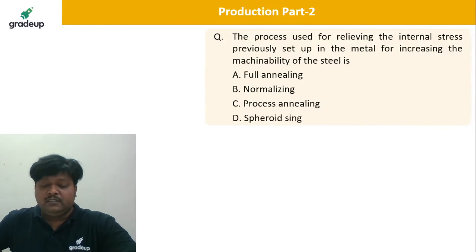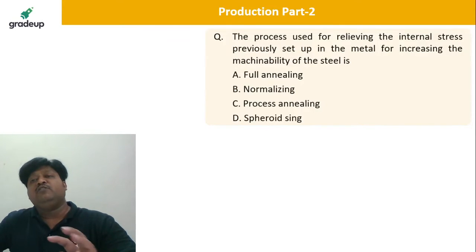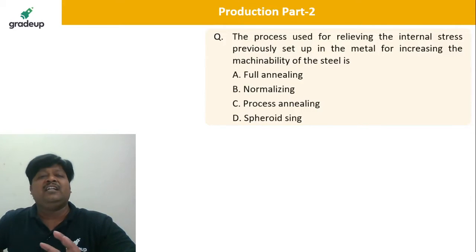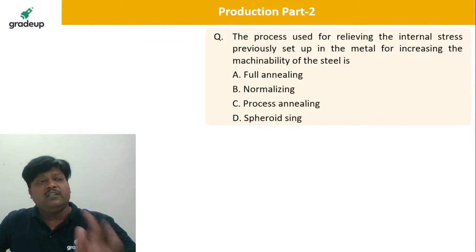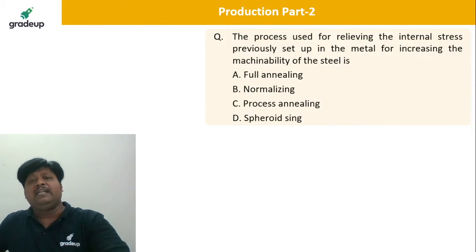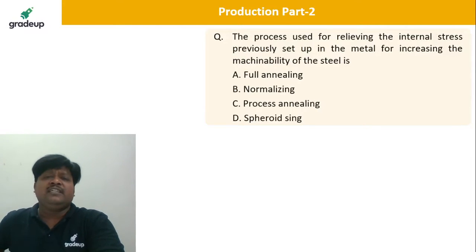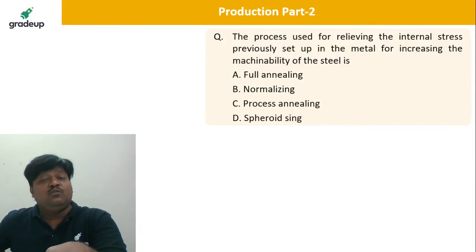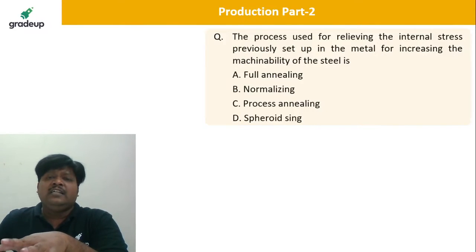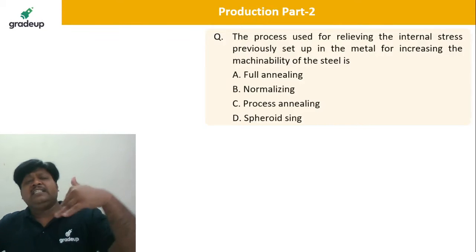So dear students, whenever you are working on the material, whenever you are straining the material, that is, say we are having some deformation in the material, some energy bundles are stored in the material, because of the work done onto the material, near about 10% of the energy gets stored in the material in the form of energy pockets or energy bundles that are known as the internal residual stresses.